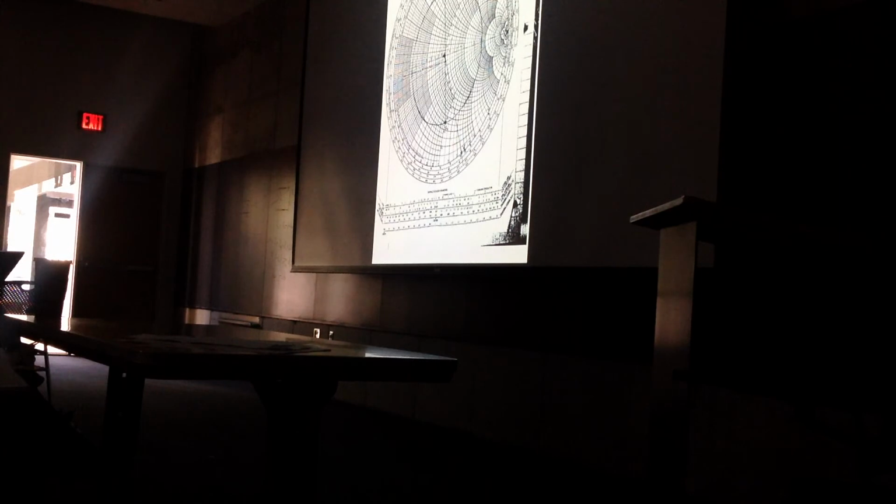And if you adjust that transmission line length, it will be on this circle here. So this big circle intersect with X equal to minus 1.5 will be the location you are looking for. So this corresponds to X equal to minus 1.5. So you need to go from the short circuit to here.